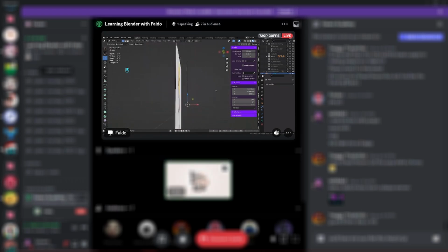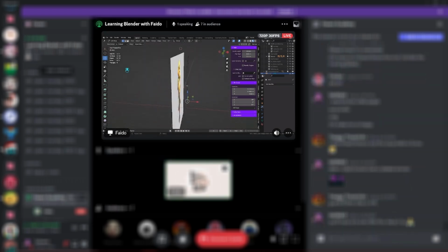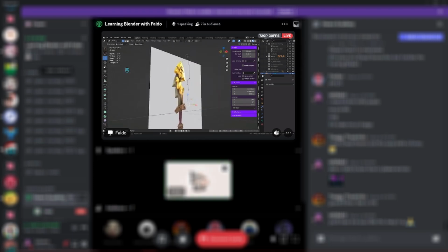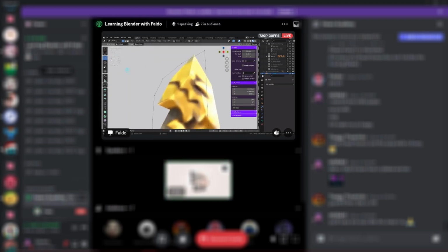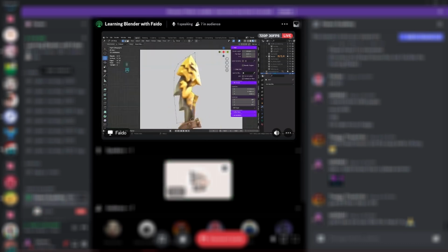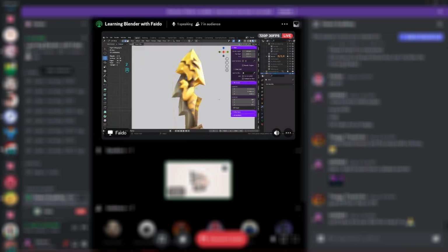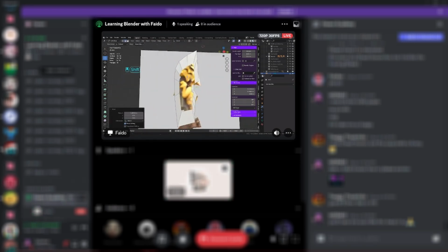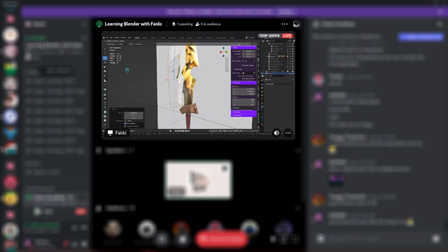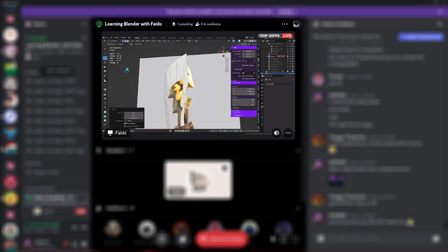So if we move the camera a bit, we now have this kind of thing, right? Right, this part is how the blade has this middle section, and here is the smaller part. You can just select everything, and then we press extrude, and then scale it down so that it goes inside of itself, and then grab it a bit, and then pull it down, something like that.